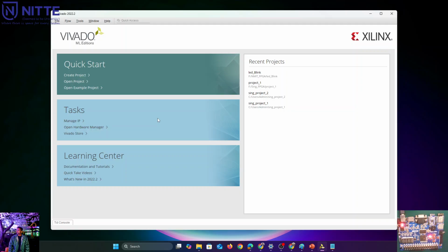Today we are going to see a very simple task. As you can see on the screen, the FPGA board hardware is displayed, and you can see my pen pointer. This LED, the last-most LED, which is silk screened as D19, is connected to T9 of the FPGA IC.